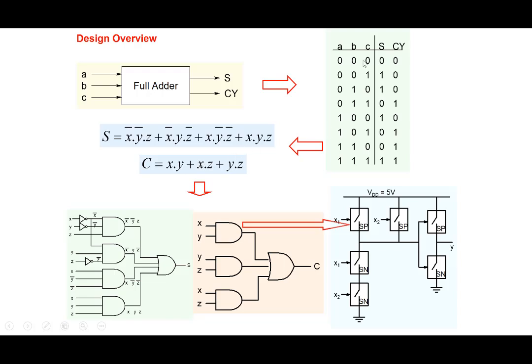And we will see that going from the truth table to a Boolean expression, this final Boolean expression is not the optimized Boolean expression. Often what you can do is simplify the Boolean expression. And if you simplify it, in the sense that by combining certain terms and using those postulates and theorems that we talked about, we can obtain a simpler expression for S perhaps. And the simple expression also corresponds to the same truth table. So we don't violate the truth table, but the expression is simple and therefore it will result in a simpler implementation. So an important part of the design of a digital circuit is trying to obtain a simplified Boolean expression which captures the truth table that we have here so that the implementation is simple. All right, so our focus then is on the Boolean expression.